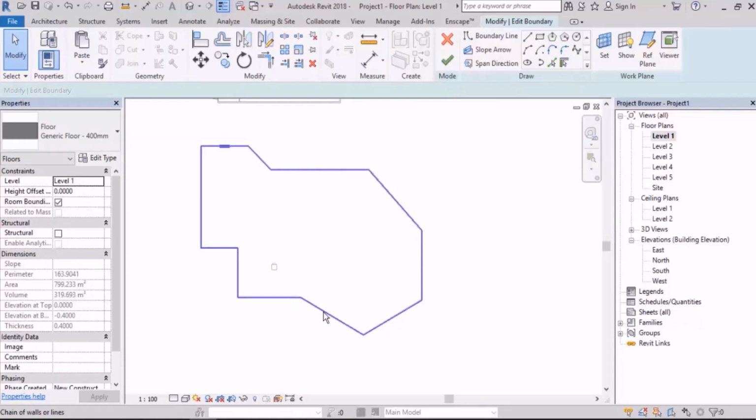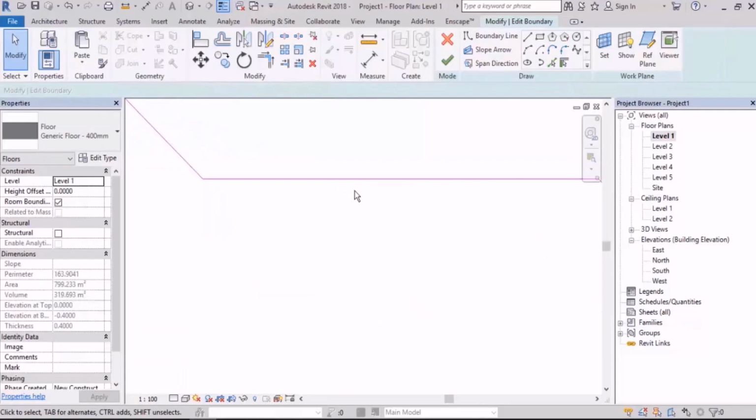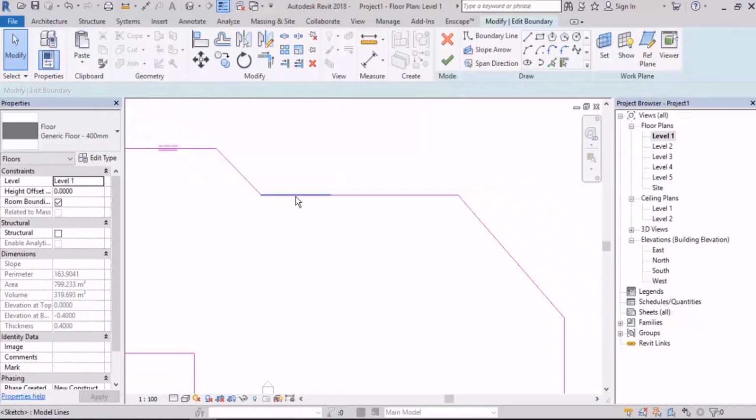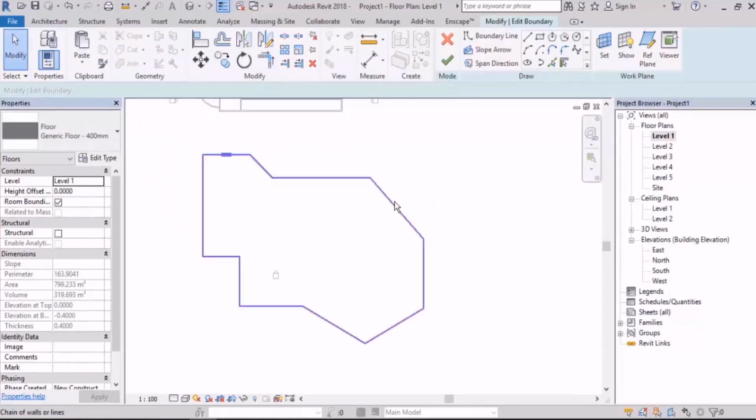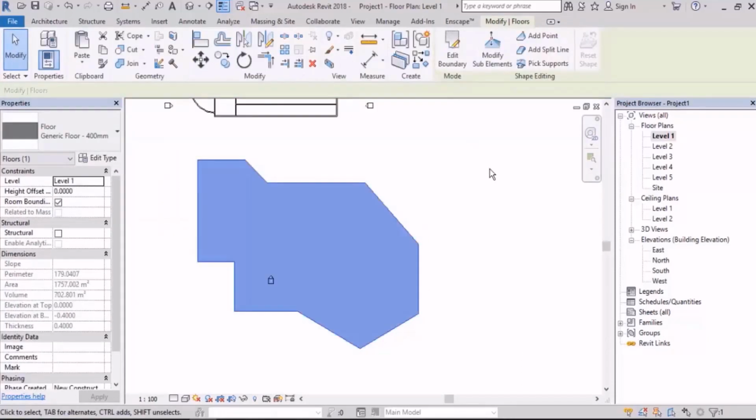But pay attention, we still have one more level. Be careful to notice weird spots, for example these two, that are different. I zoom in and I see, yes, here is an overlap too. You can delete one of them and then continue the other one, or delete the overlap part. I tap again and it looks perfect. Well, I told you the golden way to edit the floors. So that was the way of solving the errors of floors.